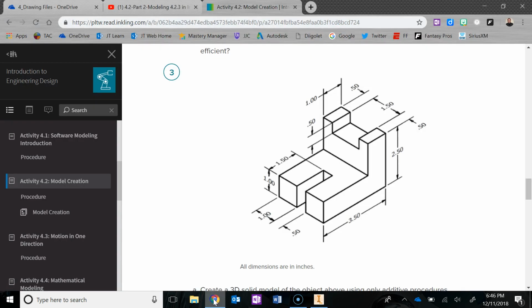We got one more subtractive method to use or integrate, and that is right here on this rectangle. We're going to do pretty much the exact same steps that we did up here, just on this top face of this part of the model. So we're going to draw a rectangle and we're going to snap it to this edge, and it's going to be 1.5 in depth and 0.5 for my width. And then those are the size dimensions, and then I'm going to provide the location dimension from this edge to this edge to make sure it's in the exact spot that I want it, and that dimension will be 1. So let's start with the rectangle.